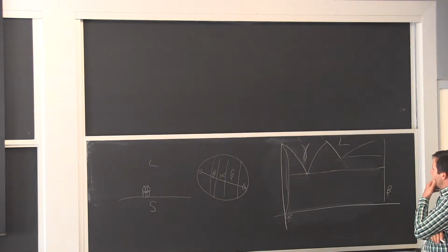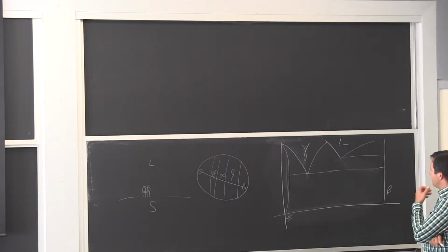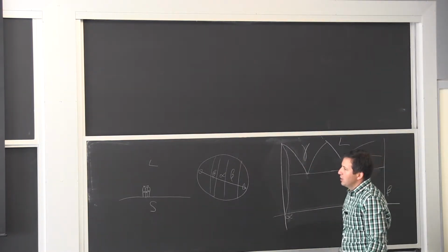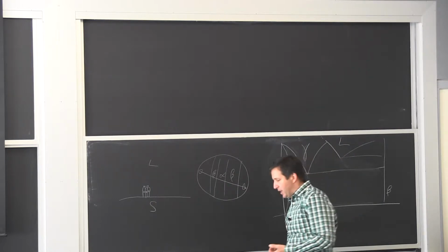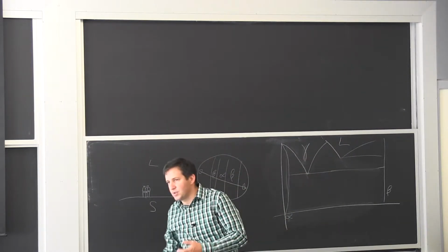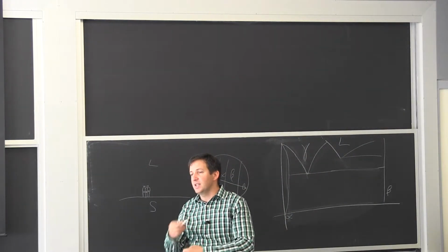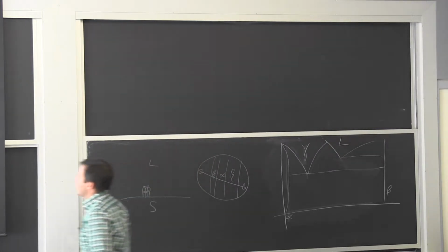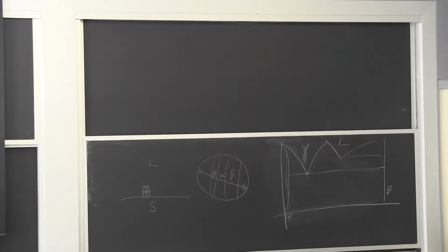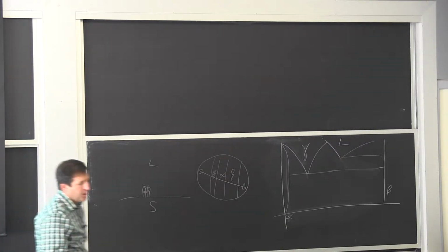You go from the liquid, you cast it, and then you heat it up. You try to be in a zone where you're very ductile and you can have all those processes of recrystallization continuously taking place. So that's why over here, in terms of strain, what you see with the stress level, the flow stress, it becomes constant.